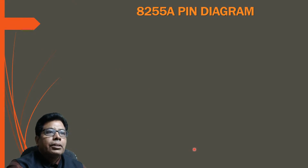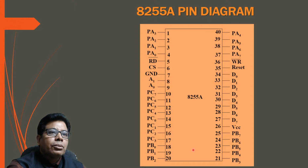Then let us come to the 8255 pin diagram. So as you can see here, the 8255 is a dual inline package 40 pin IC. So 20 pins on this side and 20 pins on this side. So here we have port A, PA0 to PA7, that is on this side. Then port B, it is PB0 to PB7, here it is situated. Then port C lower is here, PC0 to PC3 and PC4 to PC7, that is the port C upper.